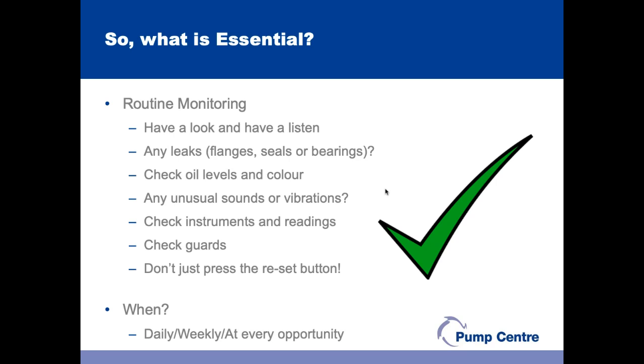And ultimately, in many cases, that leads to a much more serious problem than the one that the pump had tripped out for. So really important, if a pump has tripped out, to try and get some understanding of why that happened in the first place. So in terms of routine monitoring, when should that be done?